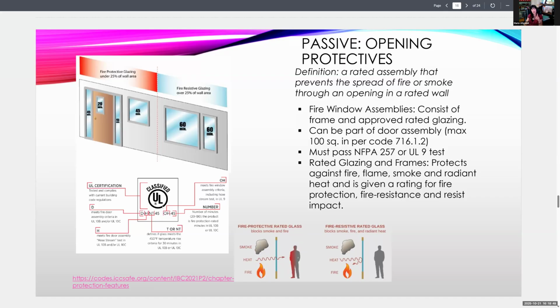Supposedly, you cannot sell any lighting fixture in the United States unless it's UL rated. That's a code. So you have to be very careful, you guys, when you are specifying lighting from other countries, like China and stuff. Because if it comes in and it's not UL rated and it catches on fire, that's on you.